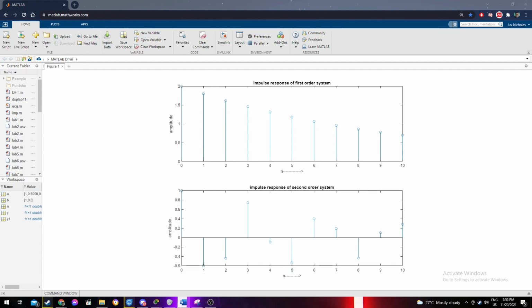In conclusion, we can see here the difference between a first order system and a second order system. A first order system has an input output relationship that can be expressed in a first order differential equation and has a commonly exponential behavior in graphs, which we can see here. A first order system is typically used to represent the behavior of many real world systems like vehicles, motors, and machines. Here, we can see a second order system